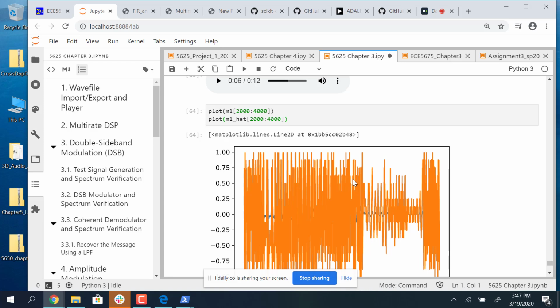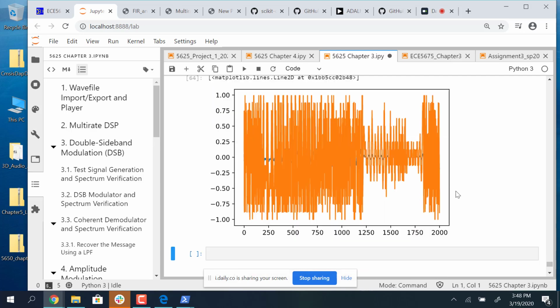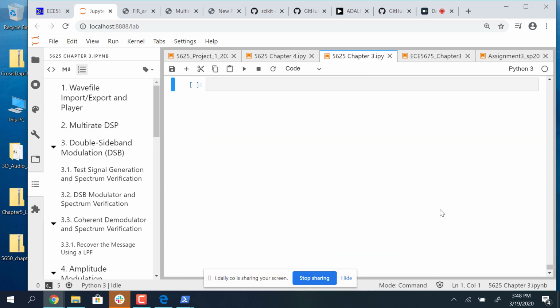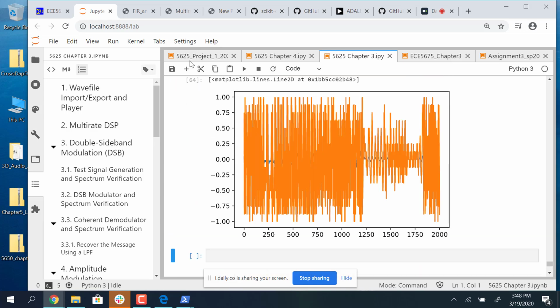I was expecting the least significant bit, and then in each packet of frame of 8 bits, the most significant bit I believe comes last, or it's vice versa. I have to look at the way I wrote the function, but at any rate, just trying to demonstrate that in time division multiplexing and serializing bits, you've got to get the framing correct, otherwise you don't know what you've got, because you have to have a marker to know how to tear it back apart again. That's all I wanted to show on that.